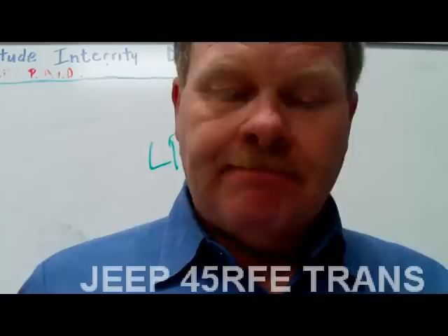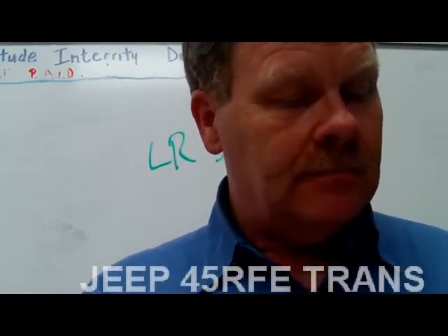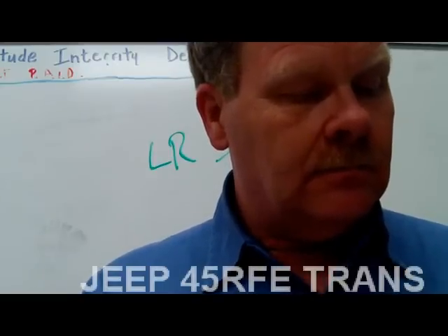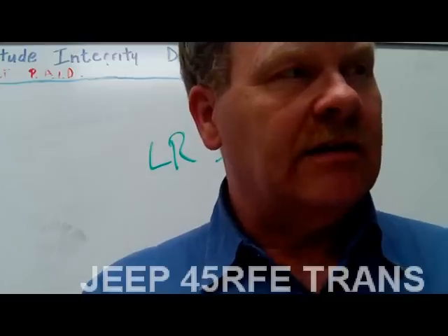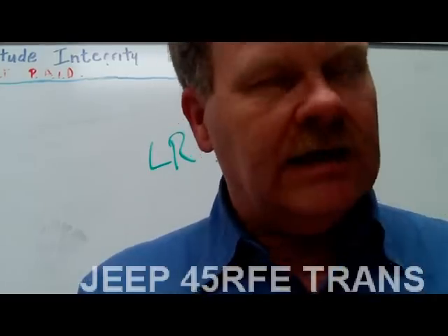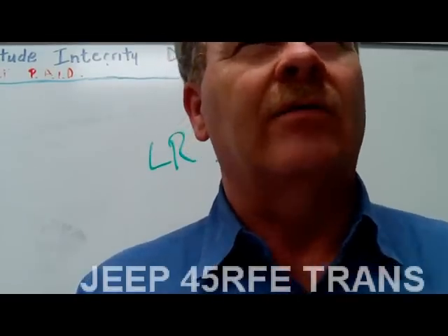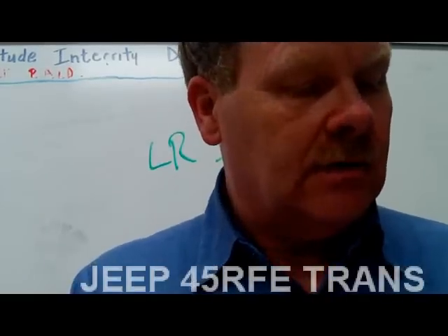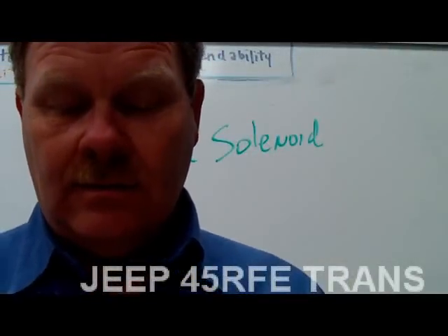Like on the Ford 3.0 motor or 4.0 motor, whenever you crank it, where the engine vacuum lines are at on the intake, I had this truck, and every time you turned it over, it cranked, and it died. Yeah, that's usually an intake gasket. And it was the vacuum cap. It can be, and also the intake gaskets underneath will cause the fuel trims to go high and make it run idle rough when it's cold. And they're not hard to change. My stepdad bought the truck, got it out of the driveway, and it died. He pulled over, put the vacuum cap back on there, and boom, it was fine.